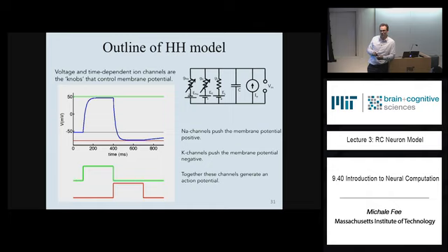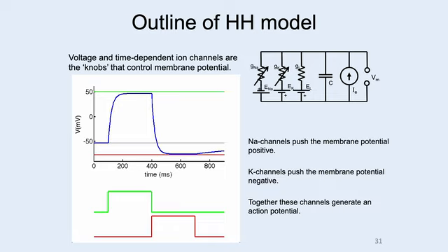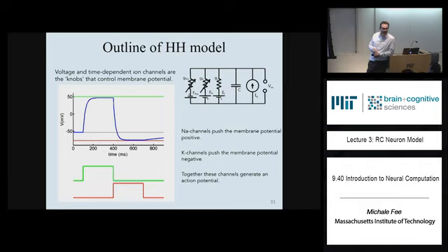Yes. So if we set both of them? So you set both of these to 0? Not 0. Yeah, the conductance is really high. That means setting the resistors really small. Exactly. Okay, that's a great question. What happens? Exactly, that's exactly right. If you turn on both of these conductances, then the voltage goes somewhere in the middle.